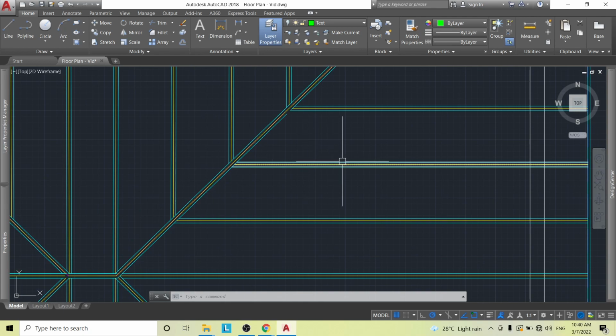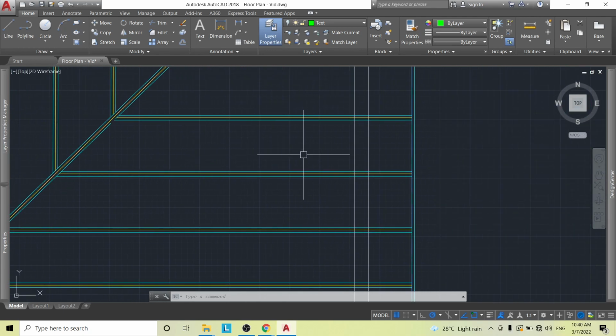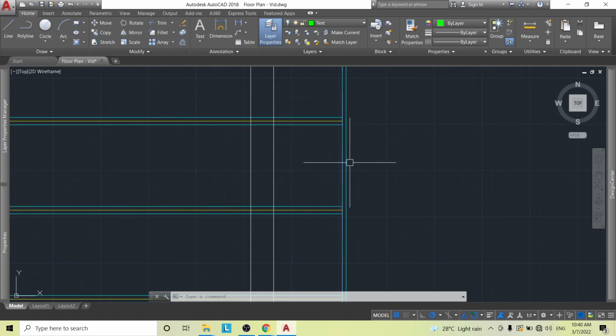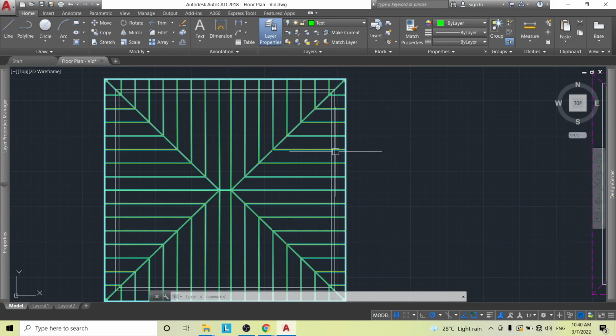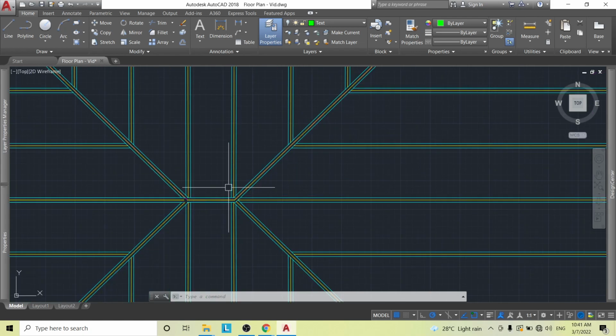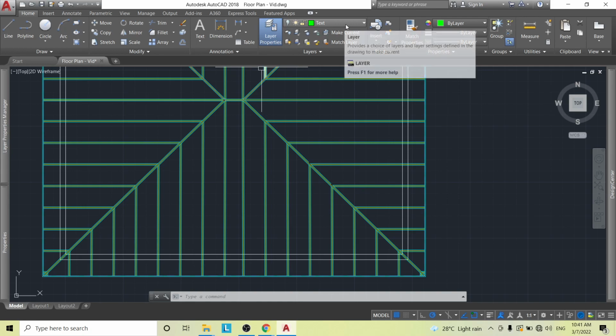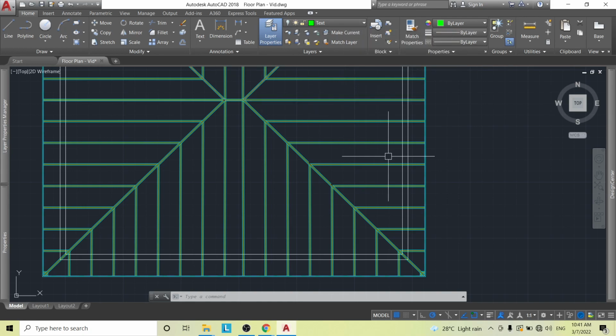Or if you look at it in metric, it should be 50 by 150 millimeters. Okay, this is your fascia board, which is 25 millimeters, 1 inch by 200 millimeters, which is 8 inches. That goes all the way around the building. And the ridge board should be the same, 50 by 150.